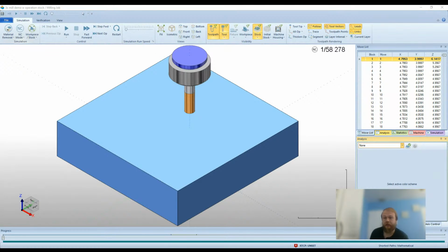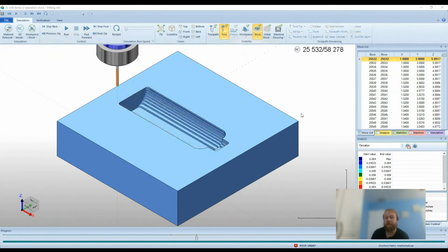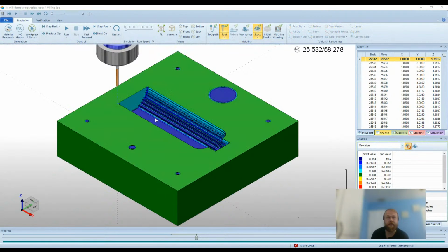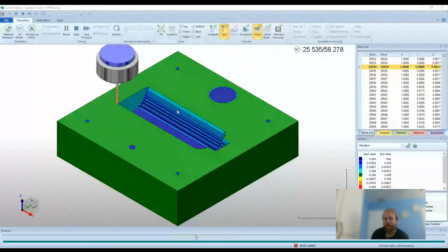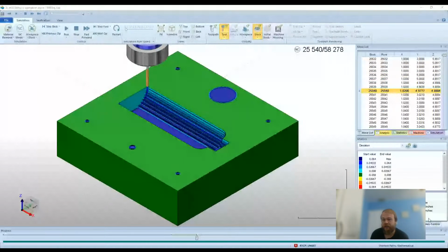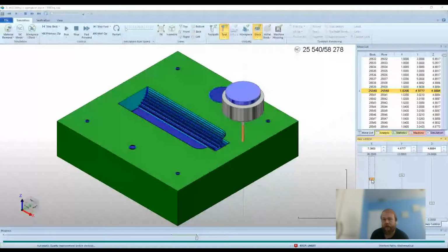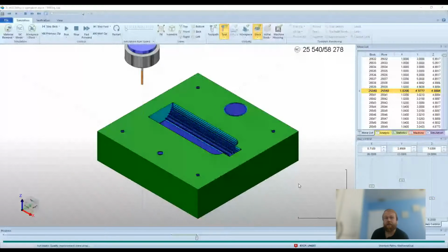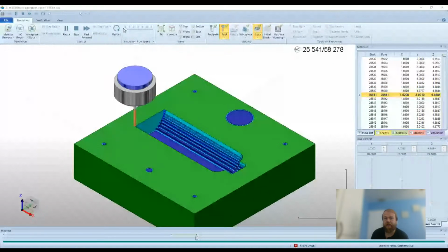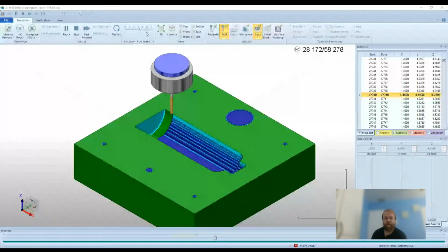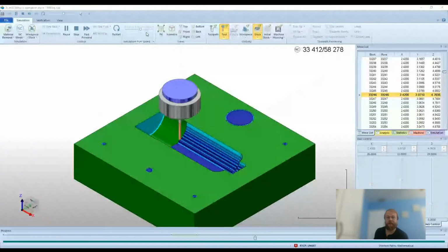Under the analysis page, we looked at the deviation report to be able to view how much material is remaining based on our workpiece that we have defined, to see if there's any remaining material from the stock left over there. And also our tool axis control here to be able to view the movement of the tool, movement of the table of the machine, and make sure that there's not any collisions between any of those movements and any other components here in simulation.